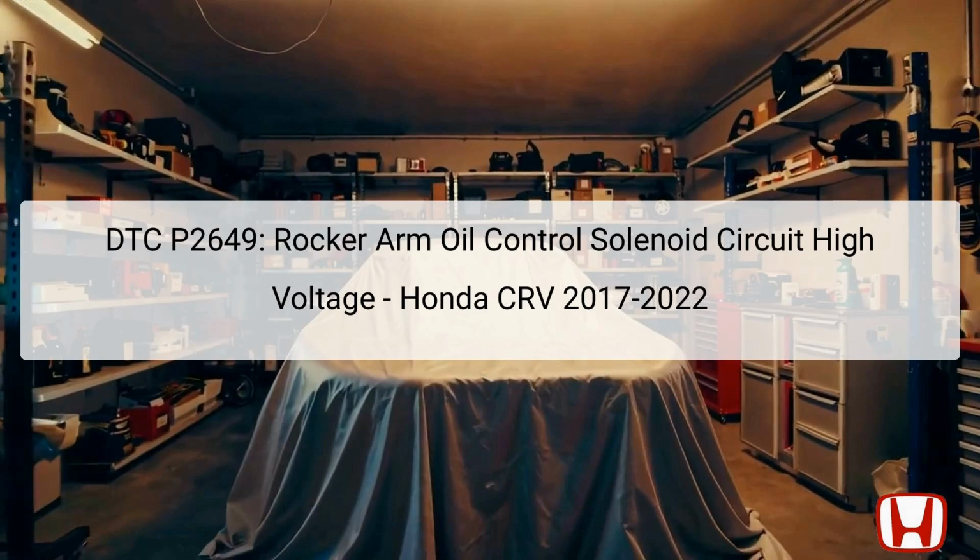The diagnostic trouble code, DTC P2649, indicates an issue with the rocker arm oil control solenoid circuit, specifically showing high voltage. This solenoid is instrumental in controlling oil flow to the VTEC, variable valve timing and lift electronic control system in the engine. Proper functioning of the rocker arm oil control solenoid is crucial, as it affects engine performance and emissions. High voltage readings can signify an internal malfunction of the solenoid or potential wiring issues.